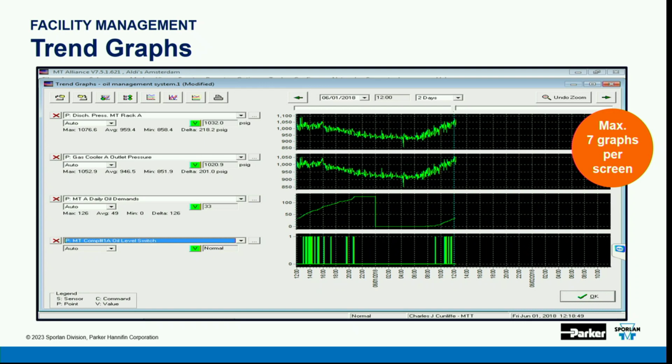What you could do with the trend graph is say, okay, let me watch this for a week and see what's going on. You don't have to buy a data logger and hook anything up with extra wires and whatnot. We give you the ability to babysit this case overnight, or a week, or a month. Say, okay, track the valve position, track the superheat, track the temperature of the case, track the saturated suction, and guess what? You save that graph for that case, and it's going to save and aggregate all of that information for you.